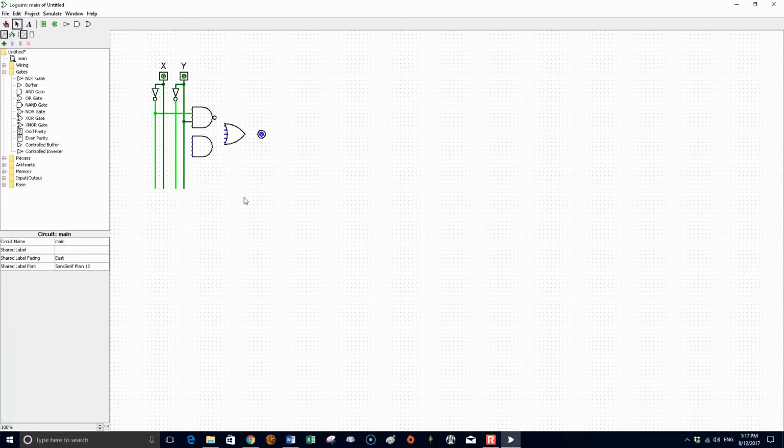That would be really inconvenient if we were constantly needing to change it to 2 or 3, but the fact is that, unlike real gates on the chips, the gates in Logisim ignore pins if you don't connect something to them. It's really important to know that's not the same as on the chips. If you have a chip with 3 inputs into an AND gate and you only connect 2 of them, the results will be unpredictable.